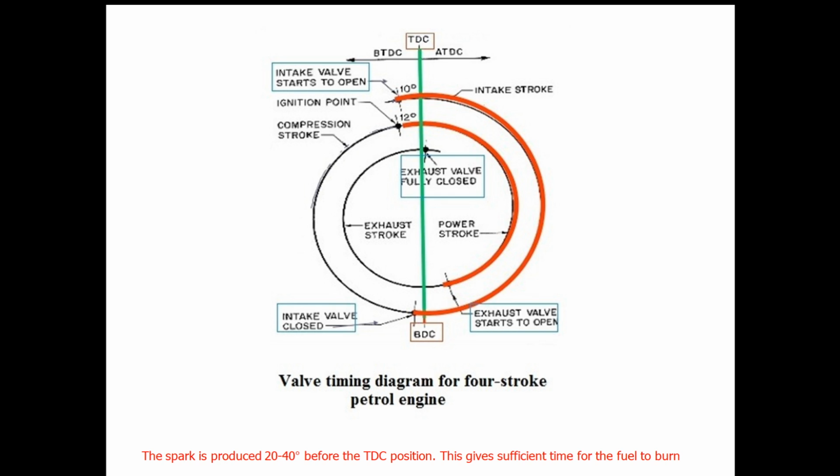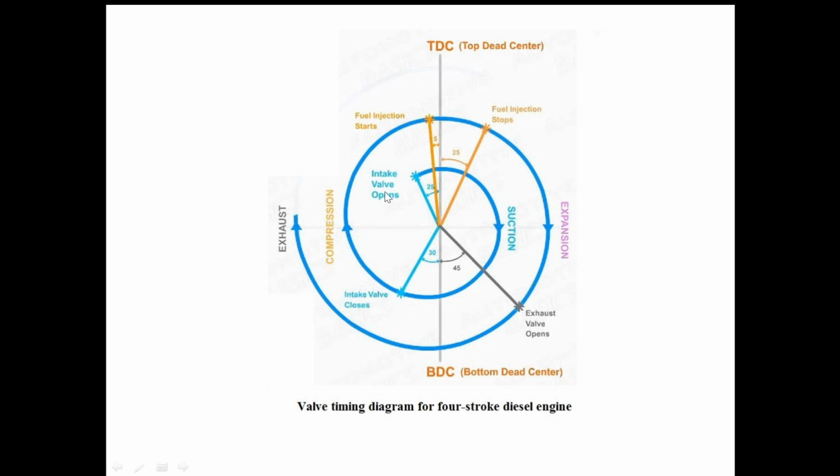The similar procedure would be adopted for the plotting of valve timing diagram for diesel engine. I will show you the valve timing diagram for diesel engine. So there will be slight difference for the angles, that's all. The procedure remains the same. So here another method is employed. We have started from the center with a shorter radius arc to plot the intake valve opening condition, intake stroke, then the compression stroke, expansion stroke,